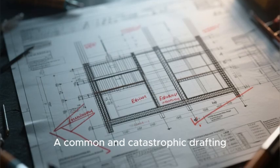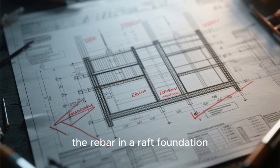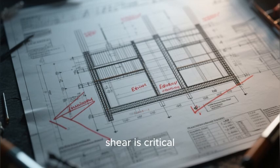A common and catastrophic drafting mistake is to underspecify the rebar in a raft foundation, especially at the column connections where punching shear is critical.